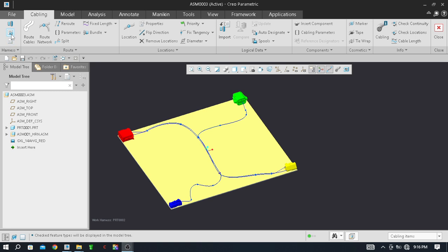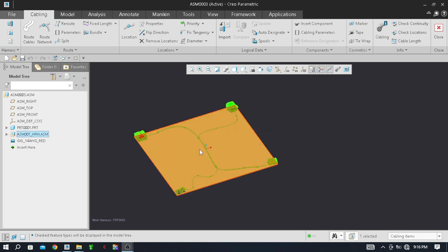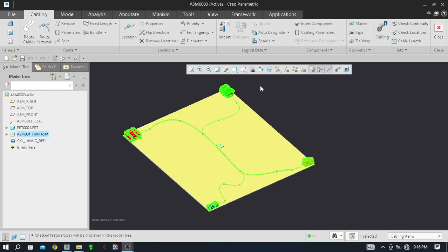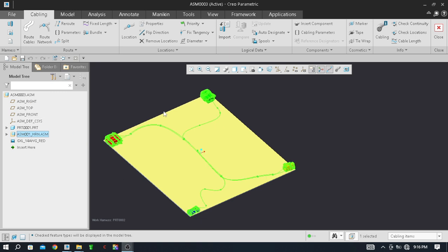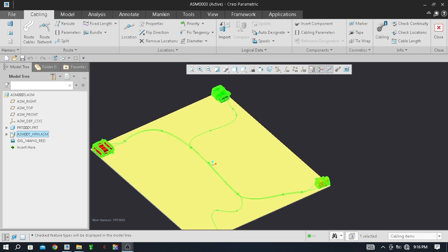For now, the purpose of this modify harness command is that we can jump to another harness assembly. It means first of all I have only one harness sub assembly, which you can see highlighted in green color. After clicking on this assembly, you can see the whole harness assembly is getting highlighted. It means I have only one HRN in this assembly.